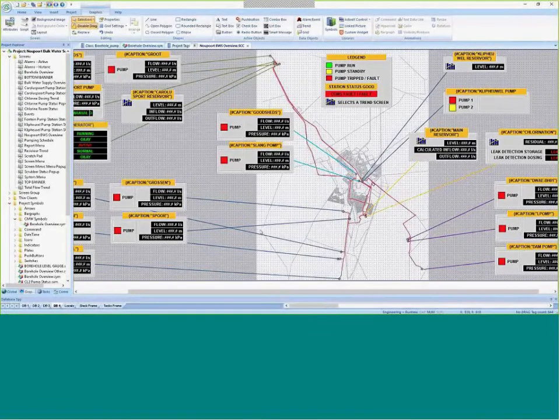And then what you can do is disable this drag. Mark, if I could have you point down in the very bottom right-hand corner of the status bar, it says no drag down there. What that does is allow you to still click on objects and configure them, get the properties open, but it prevents the objects from being moved on the screen, so you don't accidentally nudge them out of the way once you have everything lined up and positioned where you want it.